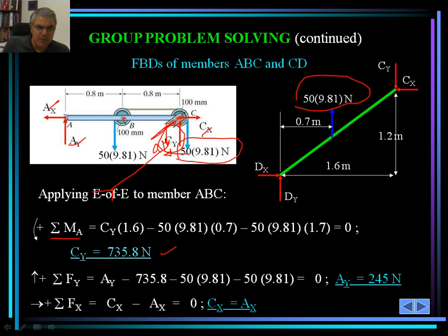so one of the components of the force in the y direction is known now. The only component in the y direction that's unknown is now A sub y. We could have done this differently by taking the summation of moments about point C and then, after calculating one of the unknowns, repeat the same procedure for the other unknowns. So both of them would work. In the case of summation of forces in the y, we set that to 0.